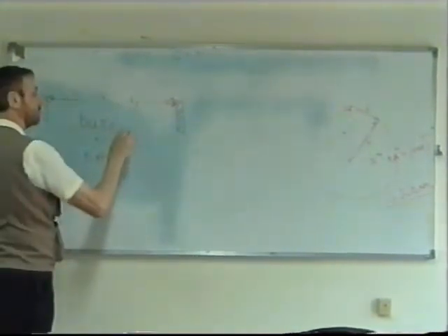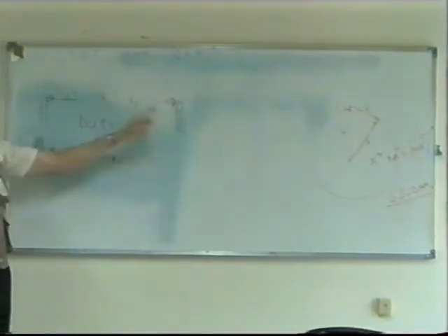Now, whoever chose the wavelength for us, we're more likely to be troubled with dust than we are with rain. This is less common, this is perhaps more common. Dust particles are much smaller than rain, tiny little particles compared to raindrops, usually. And the microwave length is chosen so that the dust particles do not affect the wave very much at all, or shouldn't. I don't know if it ever goes off under a very strong dust storm. Maybe it might, but usually it shouldn't affect it. So that's how the manufacturer's chosen the wavelength for us.